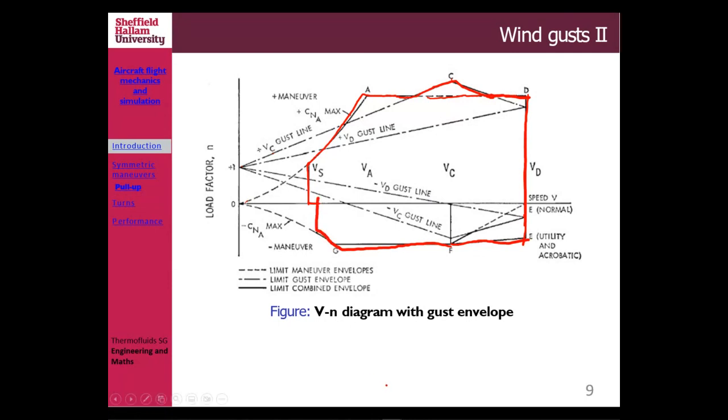of the VN diagram. Okay, so as I said, we're going to talk about that in the tutorial. I remember there are questions about this, and we're going to talk about this further in the tutorial. But as I said, if you are an aircraft designer, you should be able to draw a VN diagram for your aircraft, considering your aerodynamics, the CS25 standard, and obviously your maximum cruise speed, which could break or disintegrate your structures.